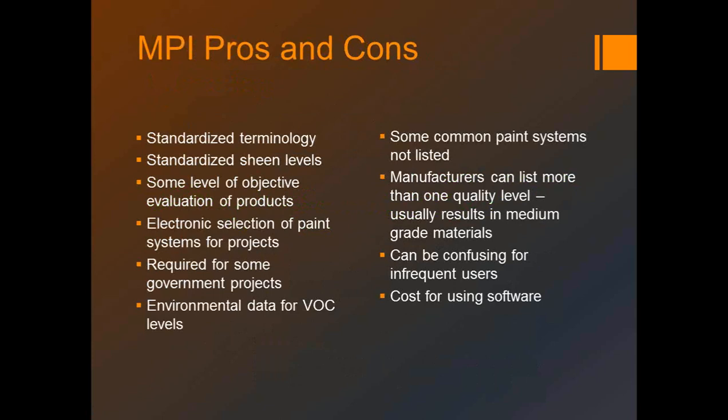Each project is a standalone normally, and you don't necessarily want to say one thing that would be either over specification or under specification for what project type that you're dealing with. So it's still very important that you know about paint quality and know what are equal products in categories. Because again, the submittal process is probably where this becomes extremely important too. Because if you leave a category wide open, as we've stated a time or two, then you're allowing for the least expensive product to be used on your project.